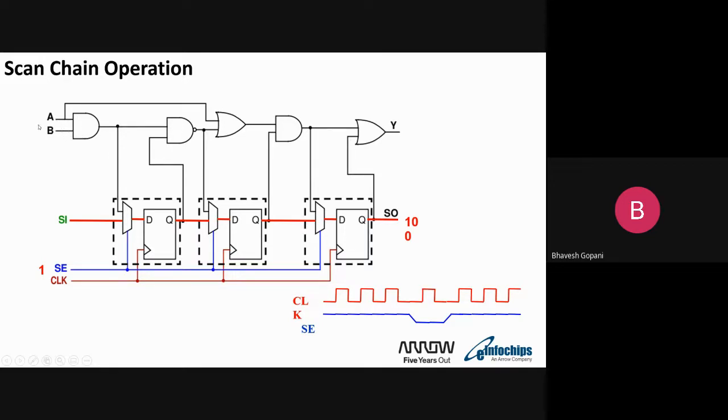If a 0 to 1 transition happens here, the output should reflect it at the same speed, or within a required range. If the output also goes 0 to 1 but only after some time, then when our clock capture happens the data is still 0 and has not reached 1, so it will be captured wrongly.